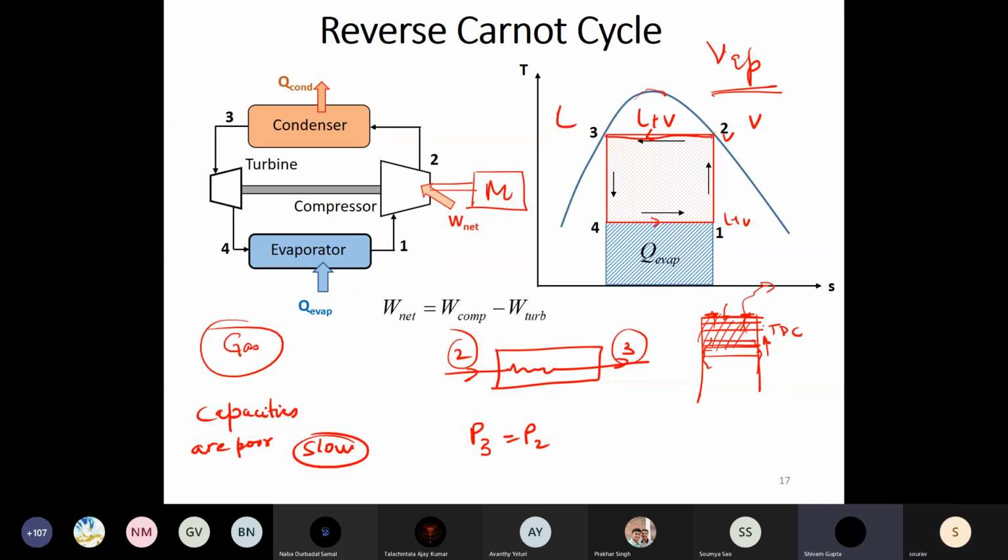Now you have a system where you have to handle both liquid and vapor. Now here comes the issue. If I design it for this operating condition, what will happen if the operating condition goes to this point? There could be changes in the operating conditions. The quality of the vapor itself in the liquid plus vapor mixture can continuously change. So I cannot design it for just one particular design condition and think, yes, I will always operate at that point. So there is a design challenge.